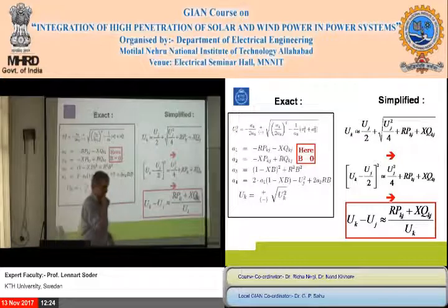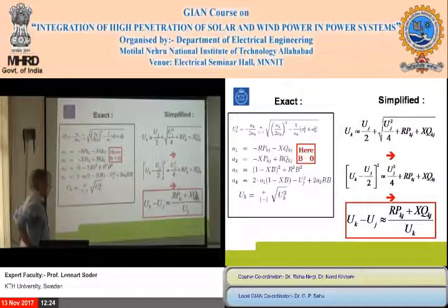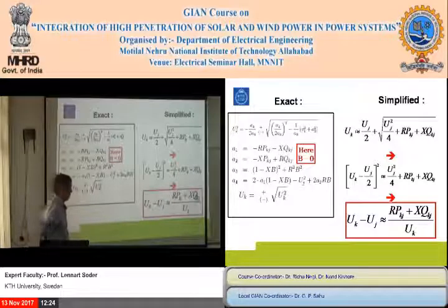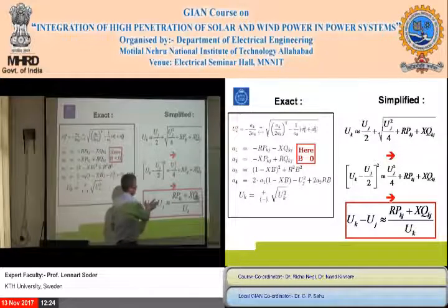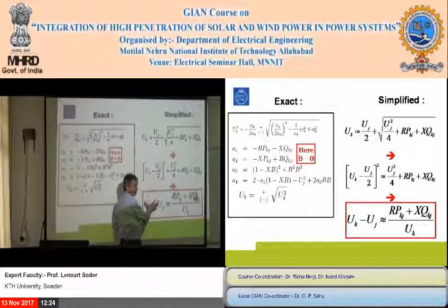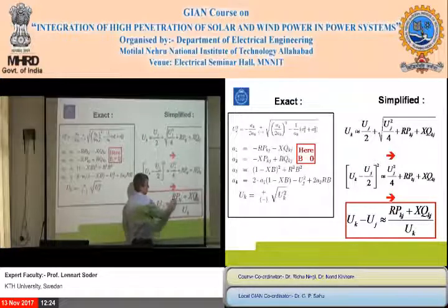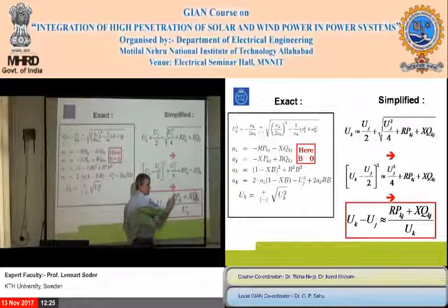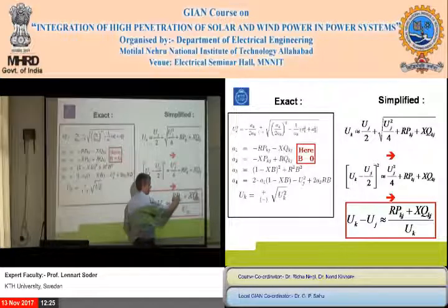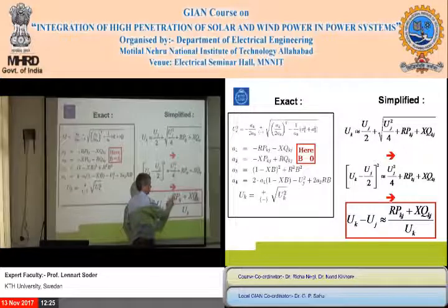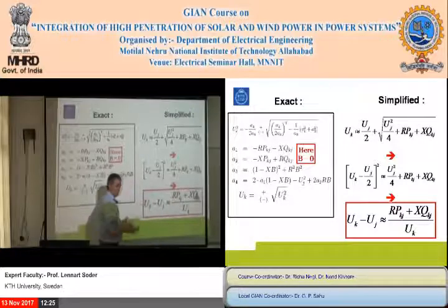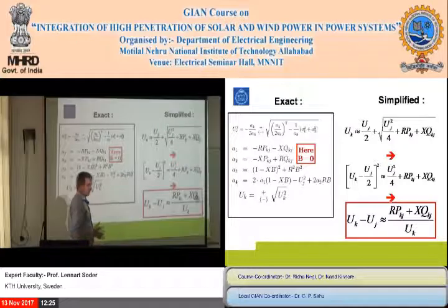This I think you have seen earlier. Here you have, and this is extremely important, that the voltage drop, if you only have P, depends on the size of the resistance. If you are producing, let's say, 2 megawatt in your wind power plants, then the question is, how big is the resistance of the grid? Then the question is, assume I get a bad voltage. Okay, I get a bad voltage. Is it controllable with reactive power?